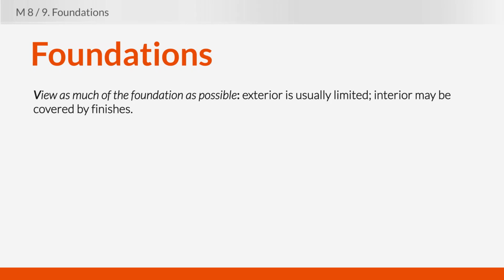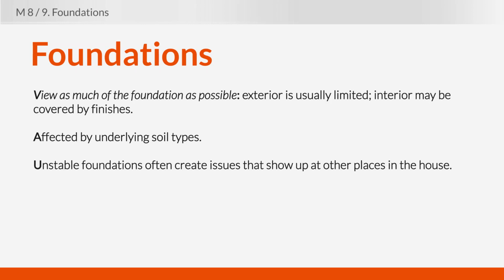Foundations are absolutely affected by underlying soil types. Unstable foundations often create issues that show up in other places in the house. In fact, almost all of the time when you find cracking in walls or cracking in brick, it's almost always due to shifting or sinking of the foundation.